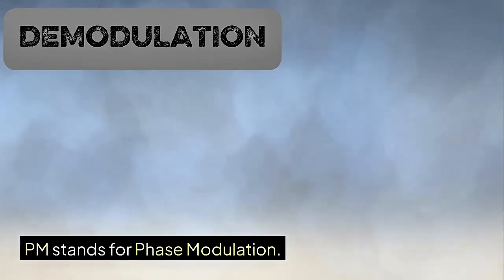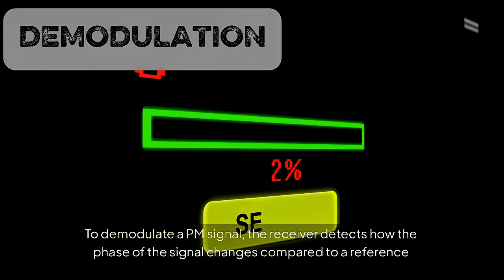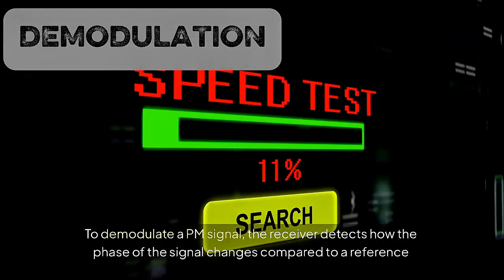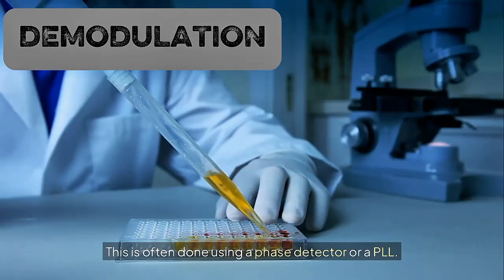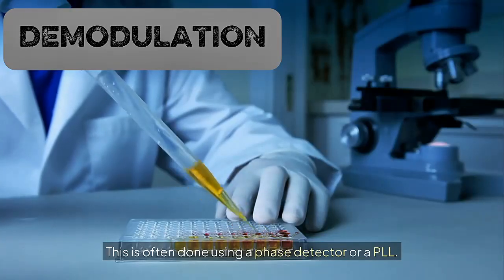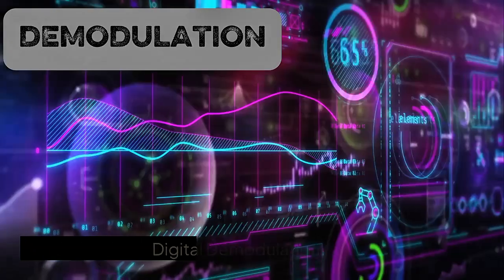PM demodulation. PM stands for phase modulation. In PM, the information is carried in the phase of the carrier signal. To demodulate a PM signal, the receiver detects how the phase of the signal changes compared to a reference signal. This is often done using a phase detector or a PLL. So, PM demodulation is based on tracking phase changes and recovering the original message.